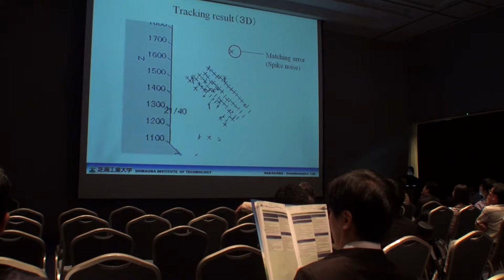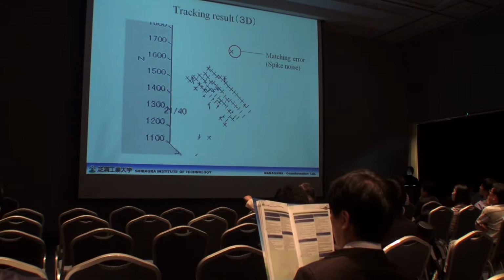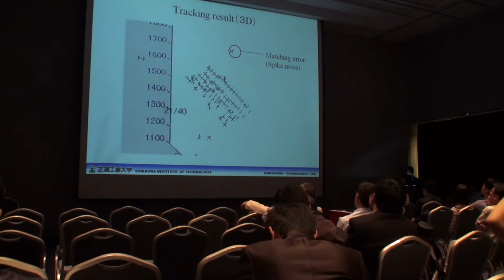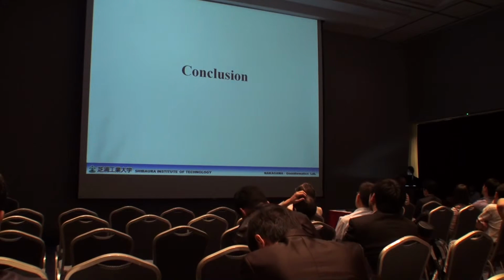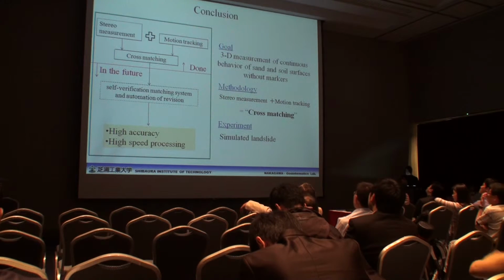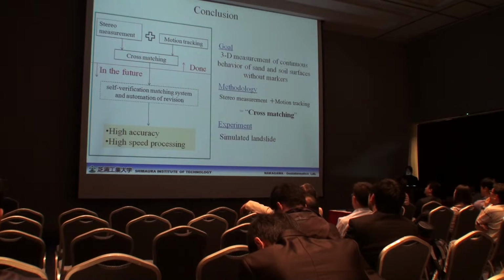Here is the tracking result in 3D. However, sometimes a matching error called spike noise occurred. This is the conclusion. Our goal is 3D measurement of continuous behavior of sand and soil surfaces without markers, and the